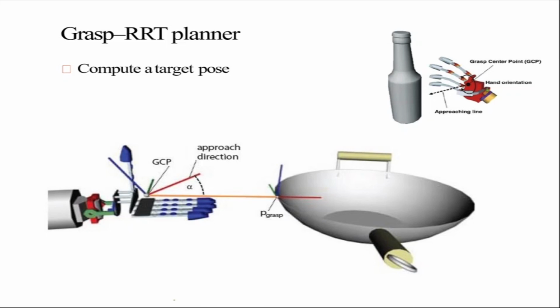So today we looked at multi-fingered robot hands and the basic mathematics and algebra involved, the concept of null space. When we are talking about grasping, mathematically it basically means that you must have forces in the null space to be positive. Only then can you have a grasp, otherwise the grasp will fail. So in terms of motion planning, grasping and then manipulating the object means that you need to have forces for moving in a particular direction along a particular path, but at the same time you must also maintain internal forces. That is what makes grasping and manipulation very, very difficult.